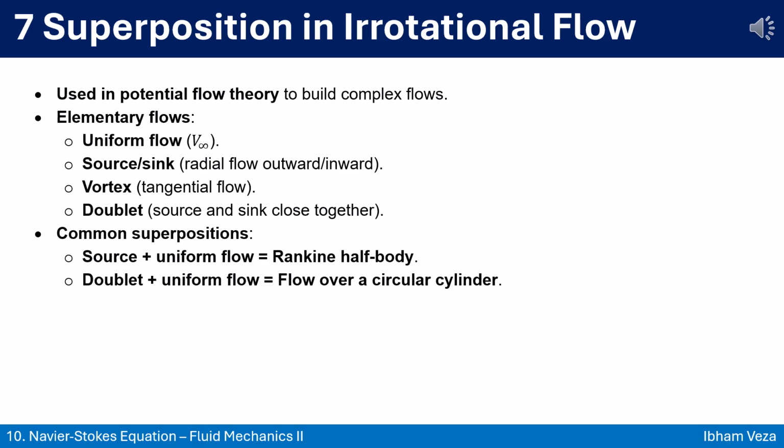7. Building complex flows from simple pieces. One of the greatest strengths of potential flow theory is its simplicity and its flexibility. Because the governing equation, Laplace's equation, is linear, we can superimpose solutions to create new, more complex flows. This is known as superposition in irrotational flow.